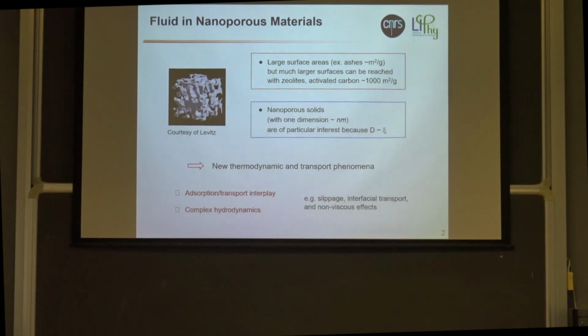I will give an example today. I'm not going into the detail because I'm going to illustrate this, but what is important is that in mechanics we usually use continuum level approaches like the Navier-Stokes equation for hydrodynamics. Here, forget about this, because at this scale, in short, the typical time scale it takes to transfer a molecule from one side of the porosity to another, typically 1 nanometer, is comparable to the time scale to relax stress in the fluid. Usually in hydrodynamics, you assume that the momentum transfer takes a long time so that you can assume that the fluid particle is fully relaxed. Here it doesn't work. That's why there's a breakdown of continuum level approaches.